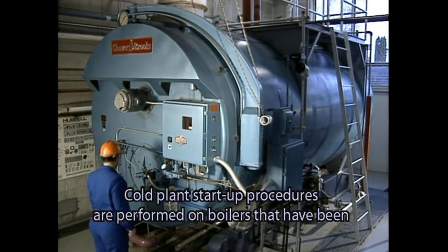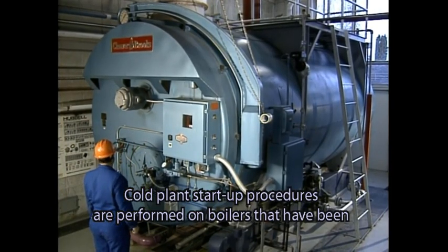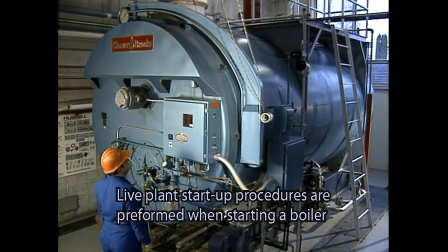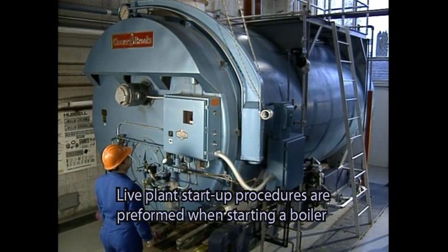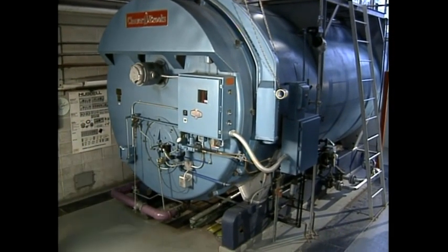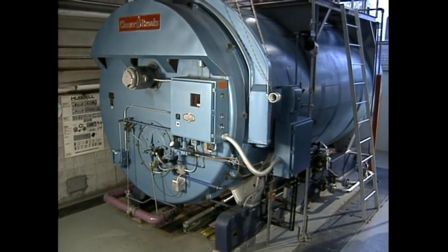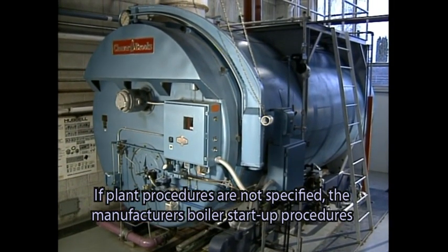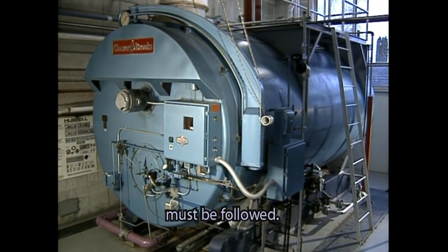Cold plant startup procedures are performed on boilers that have been out of service for more than 2 days. Live plant startup procedures are performed when starting a boiler with other boilers online. If plant procedures are not specified, the manufacturer's boiler startup procedures must be followed.